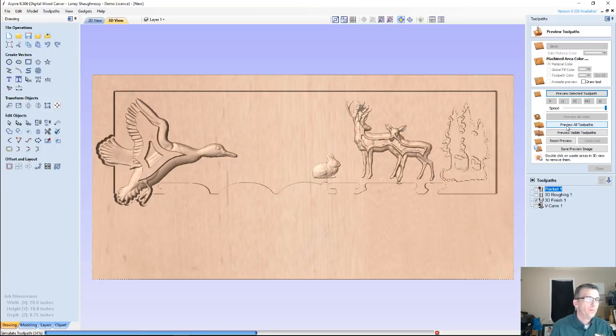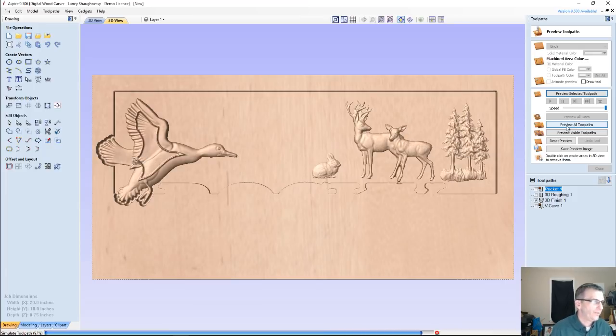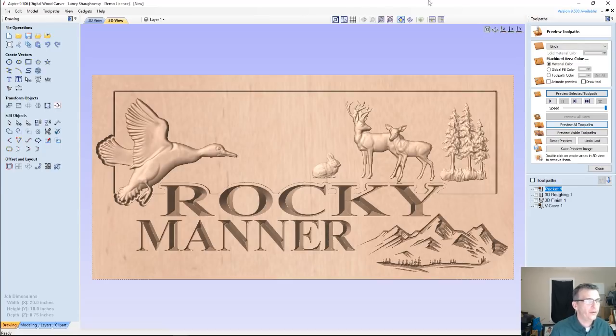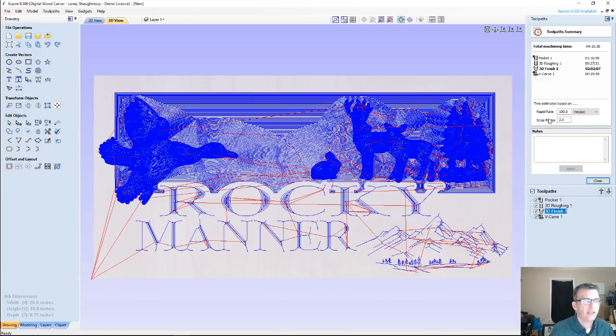Okay, if you were starting at the top of your board, if that was your Z0 touching off, then your cut depth for this pocket, so that you're doing a pocket cut versus a 3D cut, the 3D is only focusing on the 3D models, which reduces our time. Our 3D finish cut by being just on the models. Let me set my times properly here.